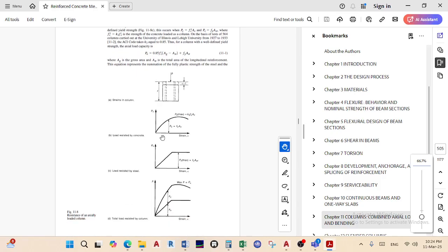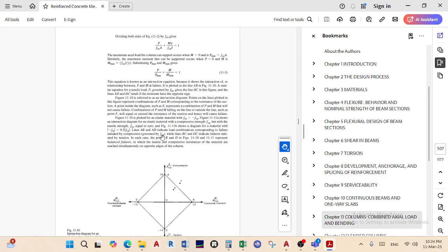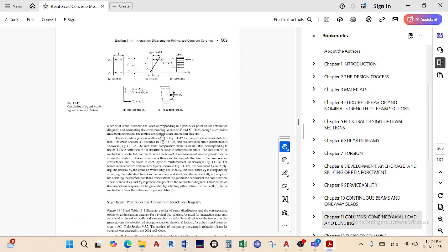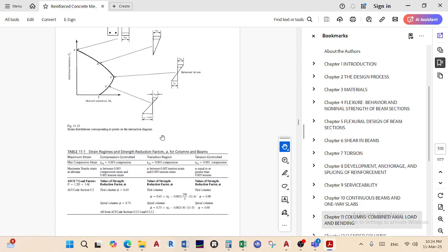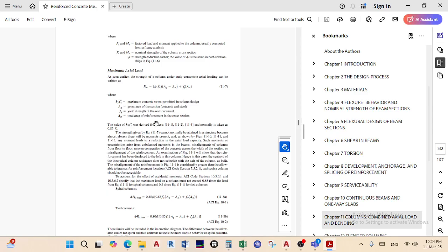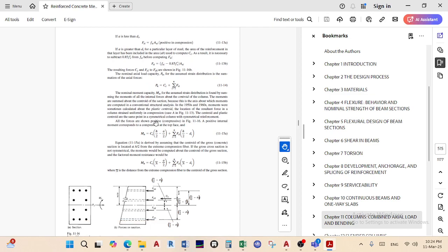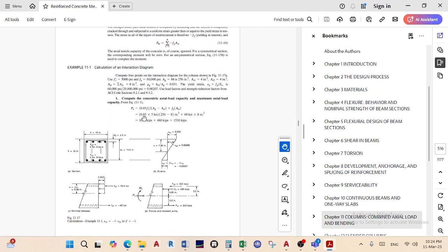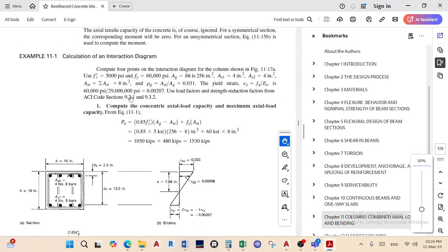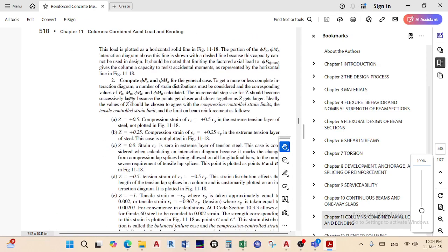You see, the utilization ratio is at the bridge now, it's at 1, so it won't pass. So this type of columns, we may have to go back, either edit the cross section of the column or play around with the layout in such a way that we reduce loading coming to this column. That's how we sort it out. So in summary, you spend a bit more time here trying to have things work because of how the loads are.